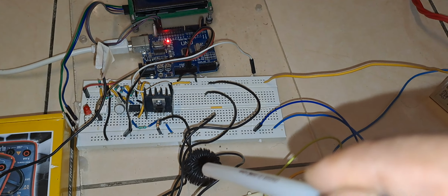This LED is getting the data and the data is fed to this optical isolator. The optical isolator output is fed to this transistor and 555 timer IC. This is the modulator unit. The modulator unit is basically generating two different frequencies, F1 and F2, based on the logic state 0 or 1. The output of this modulator unit is fed to this power MOSFET.